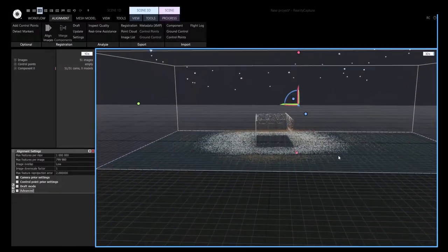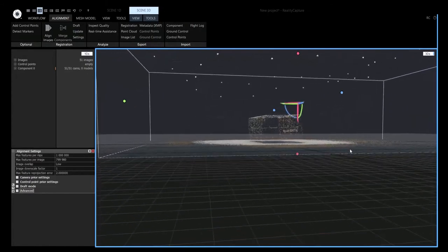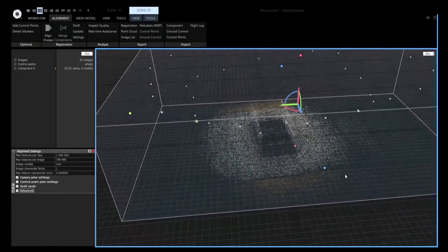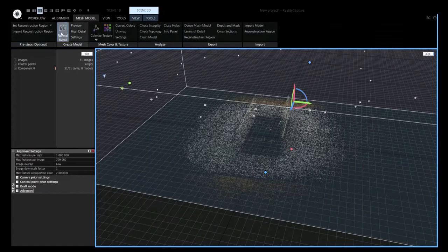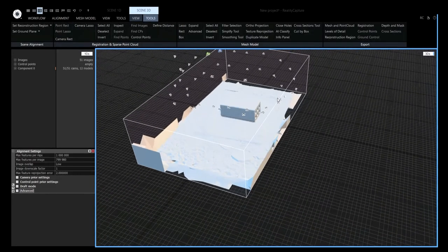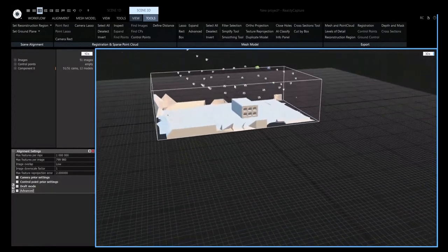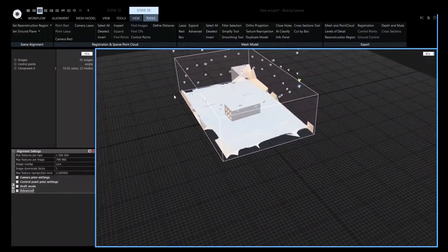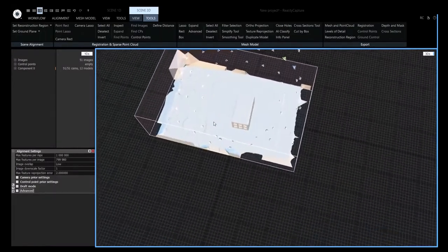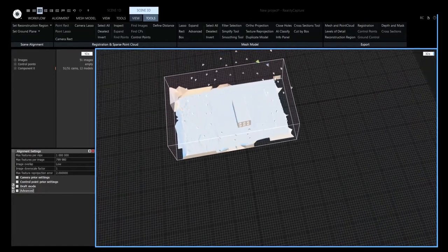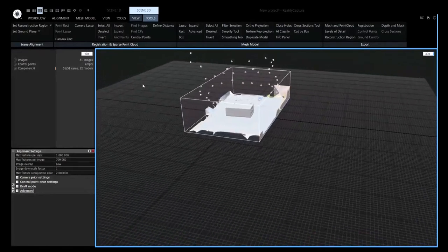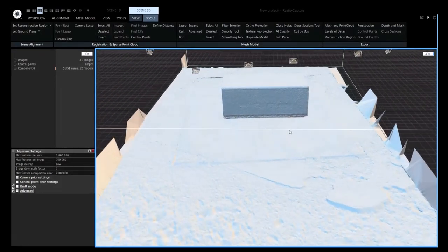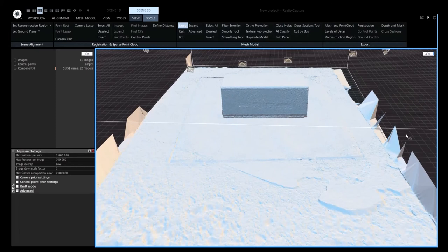Processing with Reality Capture. Insert the captured images into the program and repeat the process, selecting the Align option, and then, if the result is correct, create the mesh in normal detail. It is possible to observe the circular path taken to capture the object at different distances and camera tilt.